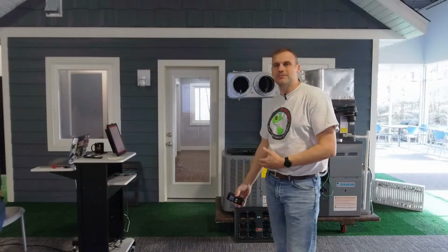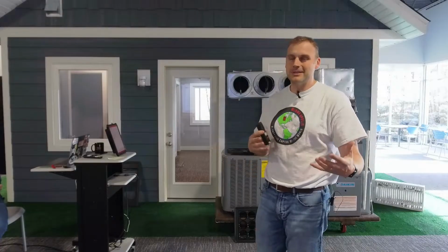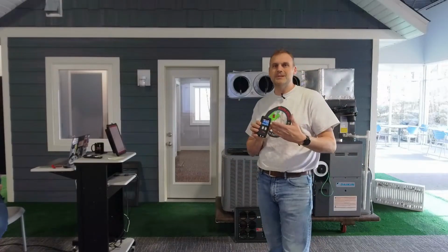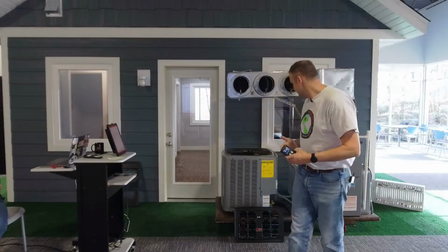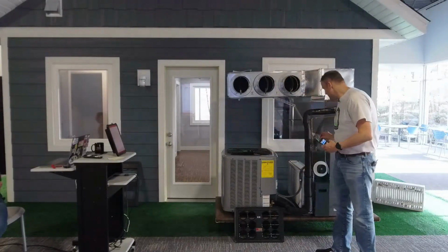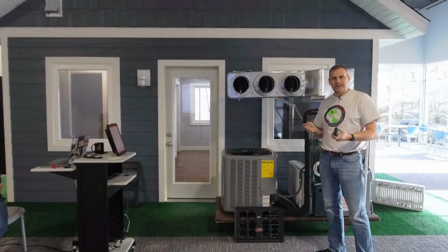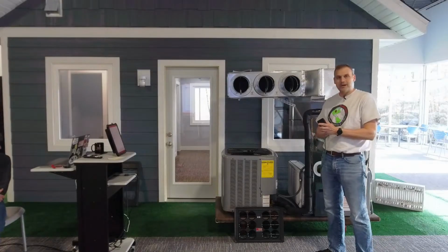We do have DG1000s that run our blower doors and our duct blasters. If you have one of those gauges, getting into the Digital TrueFlow kit is essentially cheaper at that point because you already have the gauge. So the kit can work with the DG8 or the DG1000. So we're going to use the DG8 today. Okay. When you do get a kit, it will come with the tubing that you will need to connect to a manometer.